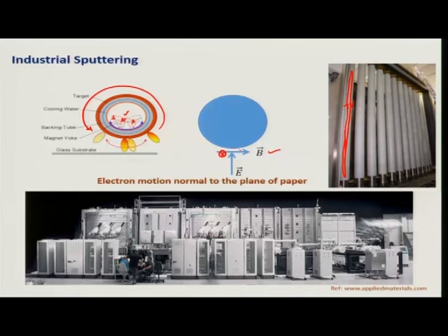There is a glass loading and unloading region here, and then there is a vacuum load lock. So, first the glass moves in, and then you have various process chambers. Okay. So, one process after another can be carried out, and thus glass keeps moving from one chamber to another chamber in vertical position, while the thin films are being deposited layer by layer.